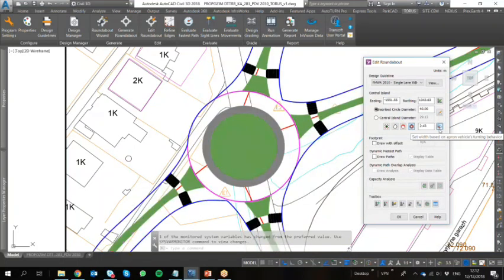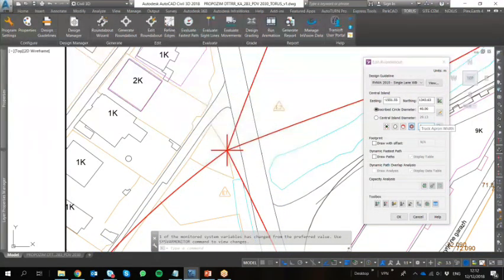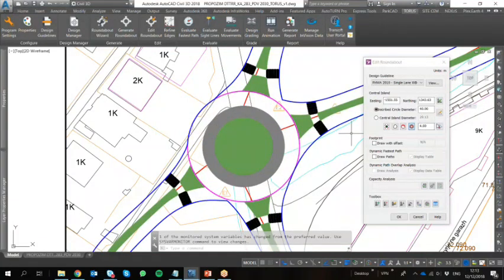However, if you want, you can turn off this behavior and just apply your own number, increasing it a little bit, 3 meters, maybe more drastically, a 4-meter wide apron. Okay, I would like this to be based on the vehicle path, so I turn this behavior off, and I ask Taurus to calculate the width for me based on that WB50 semi-trailer and the off-tracking, the swept path requirement of that.